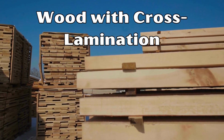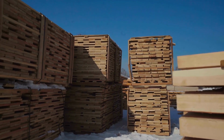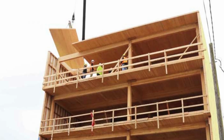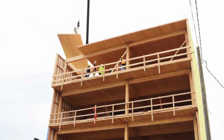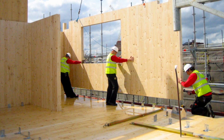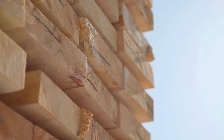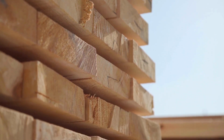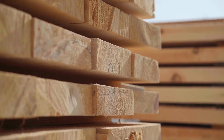9. Wood with cross-lamination. Wood planks from pine, spruce, or larch trees that are created and kiln-dried in a factory off-site are used to construct cross-laminated timber buildings. After stacking the boards into layers, manufacturers can vacuum press them to produce a solid hardwood panel. The manufacturer will frequently alter these panels so that they have a specific number of planks depending on the anticipated load capacity of a building.